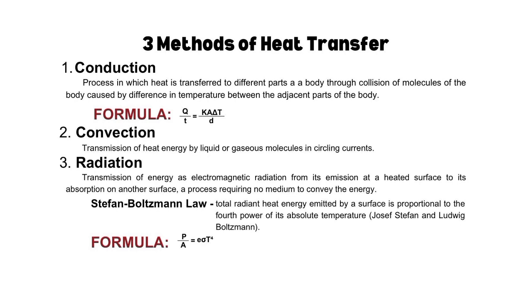Finally, we have radiation. Unlike conduction and convection, radiation doesn't require a medium to transfer heat. Instead, it involves the emission of electromagnetic radiation from a heated surface, which is then absorbed by another surface. This process follows Stefan-Boltzmann's law, stating that the total radiant heat energy emitted by a surface is proportional to the fourth power of its absolute temperature.